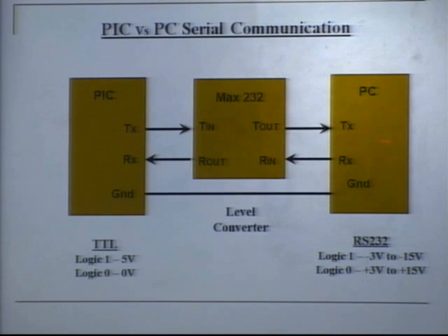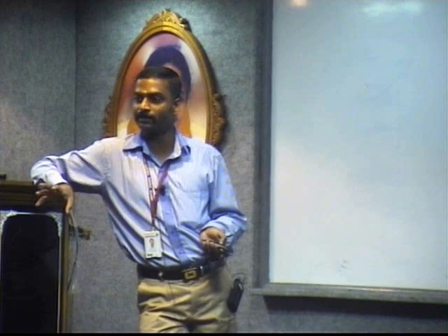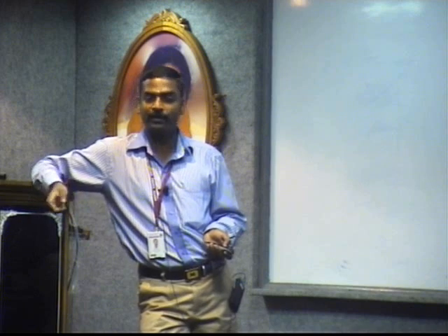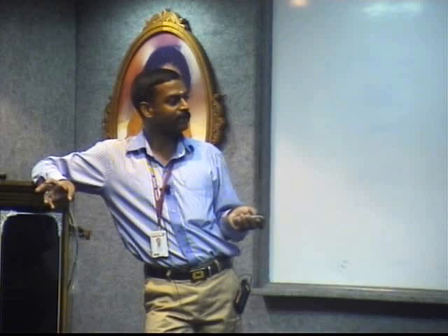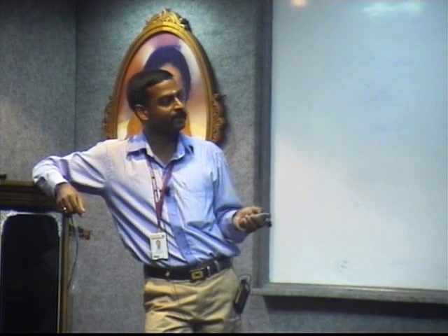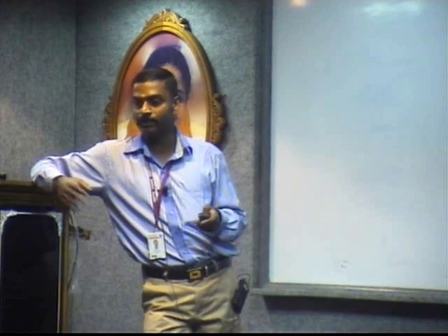And other than PC, there are so many other modules which have a serial interface. For example, wireless transceivers, RF transmitters, have you seen? RF small transmitters. In toy cars their transmitter is there, no? Wireless. All that is working basically on serial transmission. And Zigbee module, have you seen Zigbee? That is also one wireless transceiver module. So Zigbee, Bluetooth, Wi-Fi, so many things are there. All these things can be interfaced through this USART. So other than PC, you can interface these peripherals also.